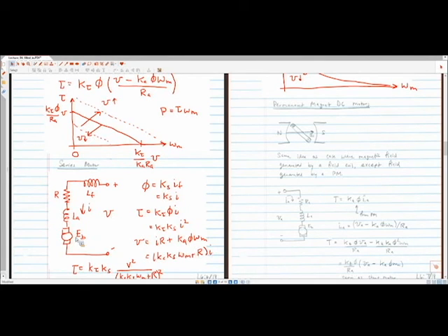Okay. Yes. For the permanent magnet, what do you mean by greater variability? Yeah. So if we have copper and we're making coils, we can count how many coils we're going to make, and we're going to get approximately the same field strength every time. Variability would be you're now making permanent magnets from rare earth elements, and that's coming from the earth, and the manufacturing processes are such they don't have as much control over that. And so you buy motor A and motor B, same exact make and model, right, but you'd have different flux in each of them.